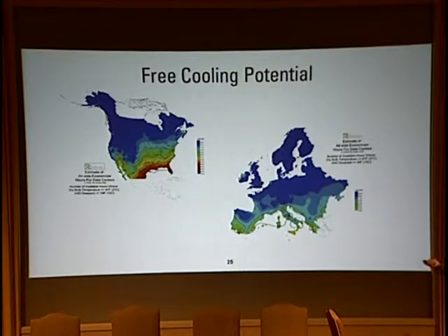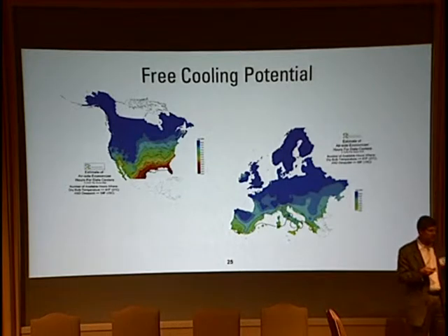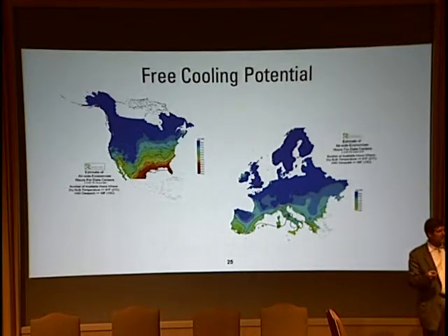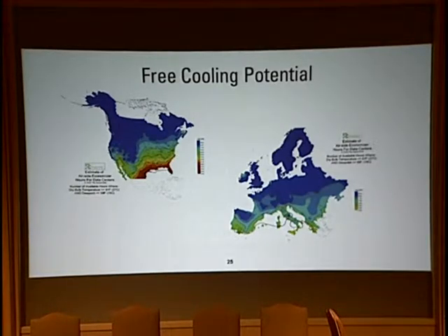If you look, Dallas is down here. We're still in a 4,000 to 5,000 hours per year range. Wayne showed you calculations that said we could get 4,600 hours per year in Dallas just by opening the windows, so that when the conditions are cool enough and dry enough that we could do things. And I just looked at the weather a little while ago. It's 86 degrees outside with a 68 degree wet bulb temperature right now. So we couldn't do direct air, but we could do water-side economization at this point, right? So here's an hour that we could get out of this.